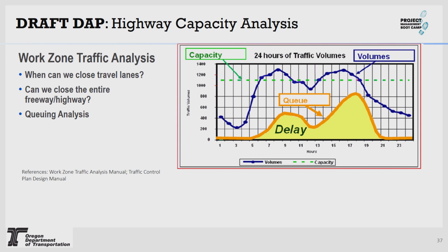Typically, 1,500 cars per hour per lane is considered to be a free flow threshold, which means if we can keep under that per hour per lane, I'm talking about 1,500 cars, not 1,500 vehicles, we typically get uninterrupted flow. However, if the demand exceeds that, we get into the interrupted flow condition.